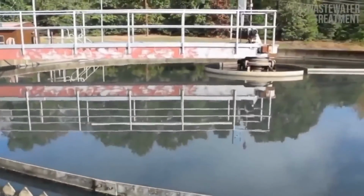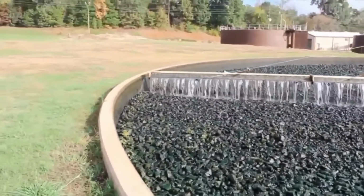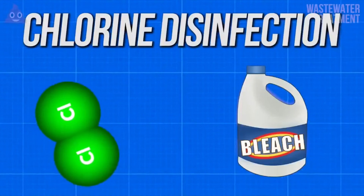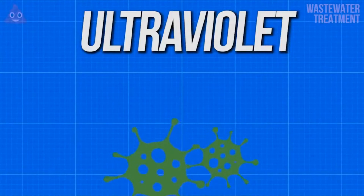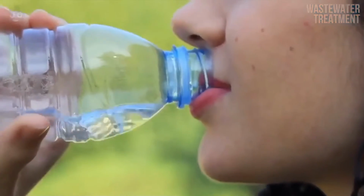The material captured on the surface of the disc filter is periodically backwashed and returned to the head of the plant for treatment. Step 7. Disinfection. To assure that treated wastewater is virtually free of bacteria, ultraviolet disinfection is used after the filtration step. The ultraviolet treatment process kills remaining bacteria to levels within our discharge permit.